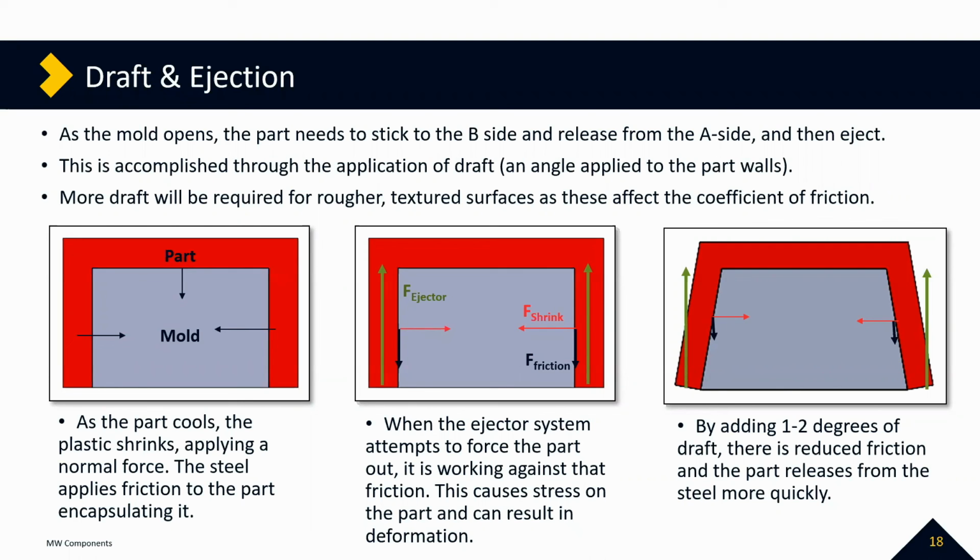We've done projects kind of like that in the past, where we have tooled up into a frame and then have had mold blocks made in the general shape of the part, and then set those back to the customer and have the customer machine out to their specification exactly what they wanted in the steel, and then we were able to take that and mold it.